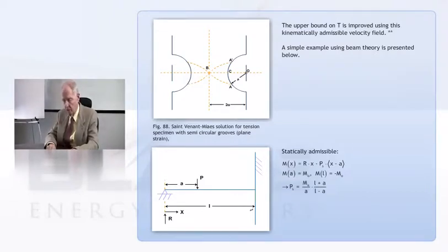But I'm going to have the limiting moment at the right end as well. If under the load P there's a lateral displacement, I have to have that limiting moment at the connection where the built-in beam leaves the wall, and I have to have a rotation at the far end.